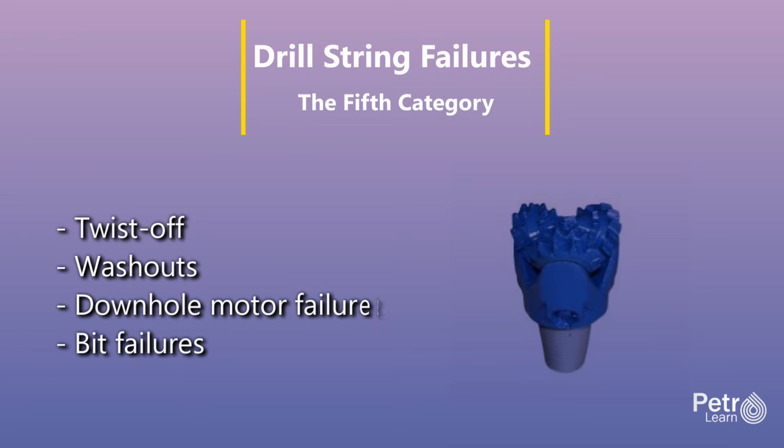PDC bits, on the other hand, often experience cutter wear, cutter breakage, delamination, and thermal degradation when drilling hard or interbedded formations or when cooling is inadequate. Both bit types can suffer from bit balling, where sticky formations such as clay accumulate on the cutting structure, reducing efficiency and causing torque fluctuations. Impact damage from drilling through formations like chert or junk in the hole can also damage cutters on PDC bits or break teeth on roller cones.